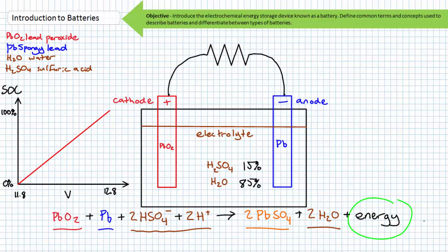This is to suggest that the nominal 12-volt value is merely a point on the operating curve of this battery and a single picture of a moving target. With the understanding of this operational range, one can approximate the magnitude of the open circuit voltage, i.e. when the battery is not connected to a load, across the terminals of a battery as a roughly linear measurement of that battery's state of charge, where state of charge, or SOC, is expressed as a percentage of the remaining energy capacity. State of charge is also sometimes called residual capacity.